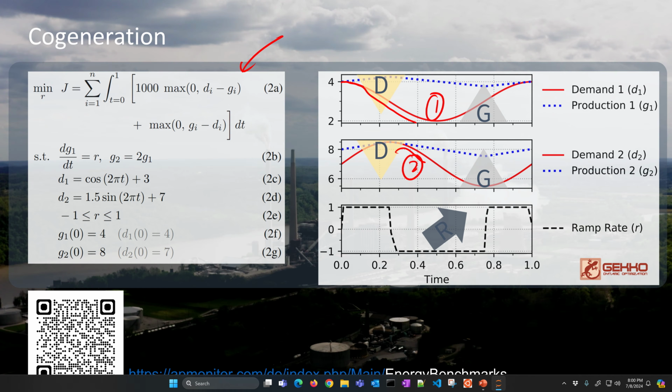And those can be physics-based. So those would be something like a physics-based model. Okay, but you could also have things like, in dynamic modeling, maybe something like an ARX or FIR model that are popular for industrial process control, where you don't necessarily know the physics of the system, but you're going to identify it from data. Now, there are many other types of models as well.